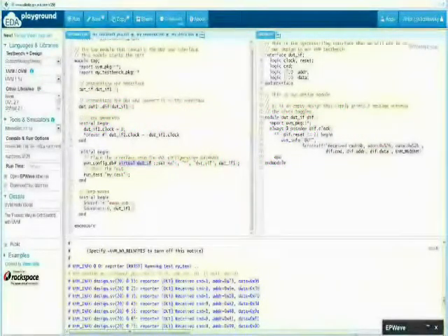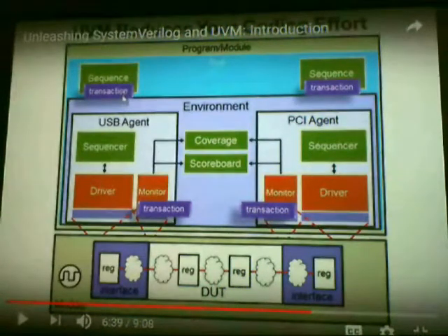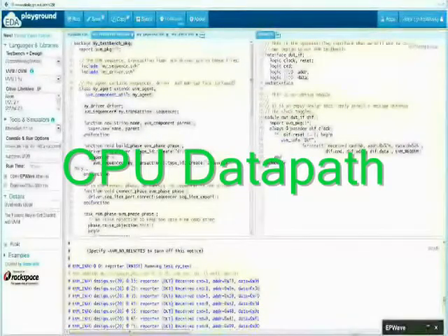Defining the processor data path. It consists of execution units such as the arithmetic logic unit and shifters, the registers, and the communication paths between them. The data path contains most of the state of the processor, the information that must be saved for a program to be suspended and then restored for execution to continue.